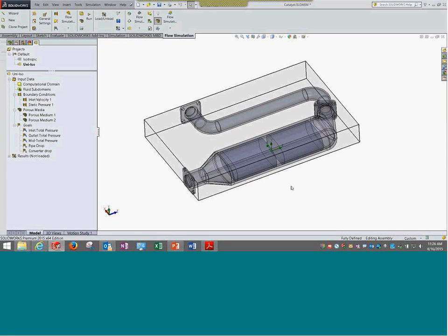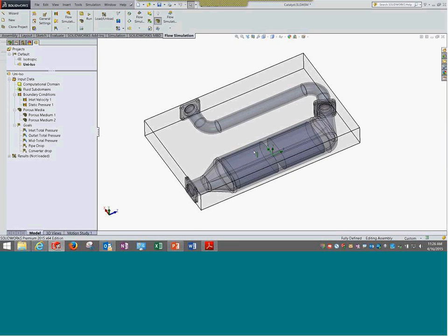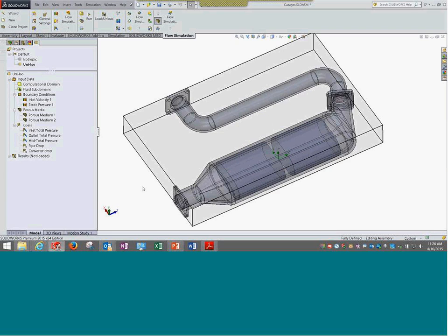One flag bearer for most flow simulations is the dummy component. So please get comfortable with the way Simulation handles it. We use dummy components at many different locations. Some are used for fans, some for perforated plates, even heat sinks use them. When you go to electronic cooling components, or rotating regions, they are also using dummy components. They are present all over.